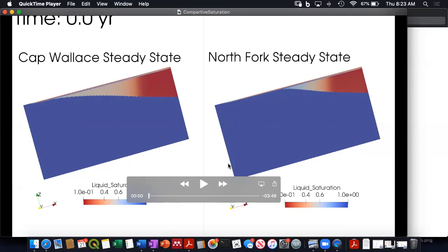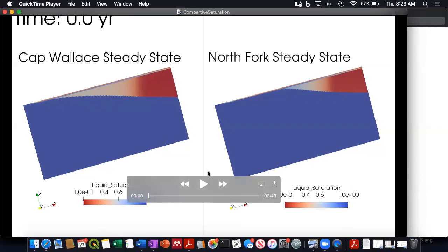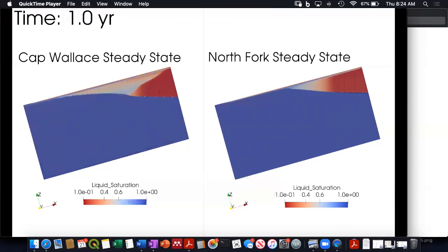Okay, so in the Northern Rockies, we get a big pulse of water in the spring during snowmelt. Then we get some smaller rain events for the rest of the year, but it's that big spring event that's the number one generator of infiltration in our system. So when I hit play, the colors are essentially the degree of saturation. Down here, this is the water table where everything is full of water, and where it's red, there's water and air in the pore space, right?